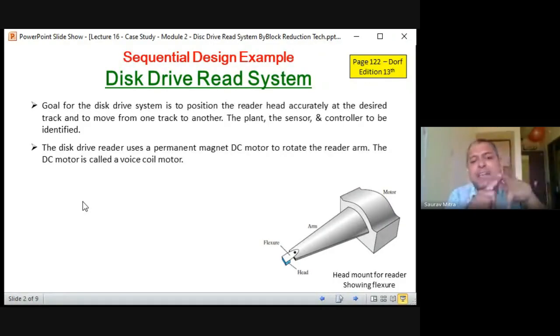Fleming's left hand rule says that the current-carrying conductor, the middle finger, is placed in a magnetic field, and the direction of the magnetic field is given by the first finger. What is the direction of the magnetic field? It is toward the south: behind there is the north pole, and here there is the south pole. That is the direction of flux. Then there is the direction of current, top to bottom, in the middle finger. That means top is positive, bottom is negative.